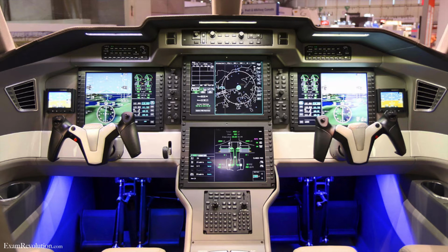Now, once again, you can see that these 2 screens are actually providing you with different types of information. The top one in this case is providing you with a map, right? And it will most probably show your track and your flight plan over there. And then at the bottom screen, you've got all your systems, right? So you can see the flaps, the fuel systems, and some pressure and your fuel flow, tire pressures, and your engine parameters and all these things. So these are all the systems with the aircraft. It's basically a view of the aircraft from the top with the 2 engines sitting there, right? And obviously hydraulic systems as well will be shown there. So once again, this can change from manufacturer to manufacturer, but the basic stays the same. It's a MFD or a ND, a multifunction display or a navigation display.